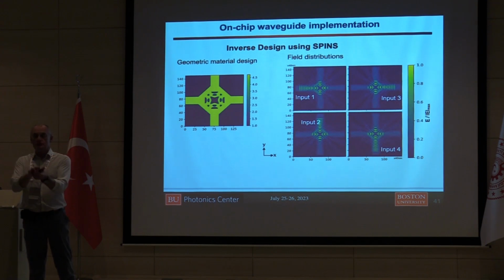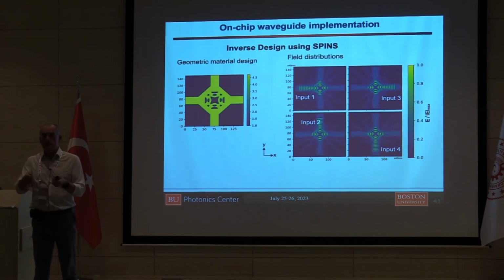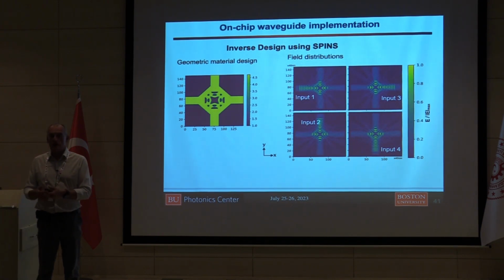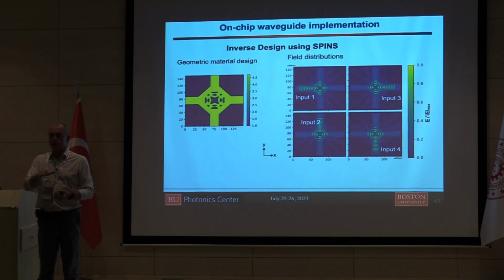You know how you do WDM filters or switches in telecom. There is a bunch of fibers, filters, and the filter tells you which frequency, which wavelengths, goes this way or that way. So they decided, okay, let's do it differently. On the chip, I have an input waveguide where the signal comes, and now I need to have like 5 channels.